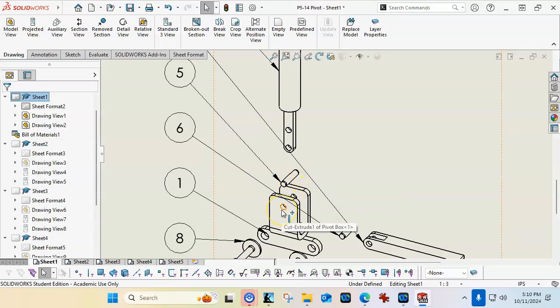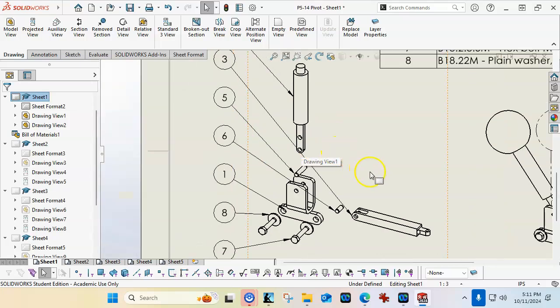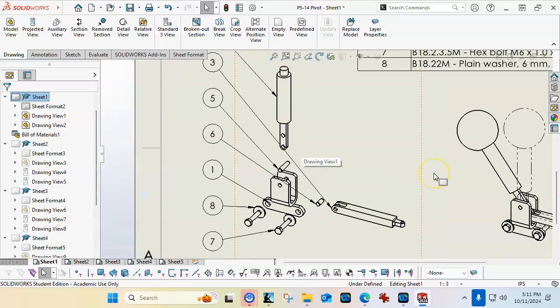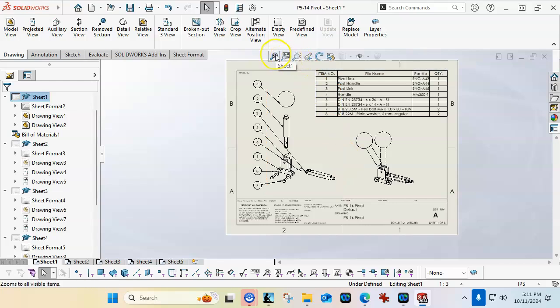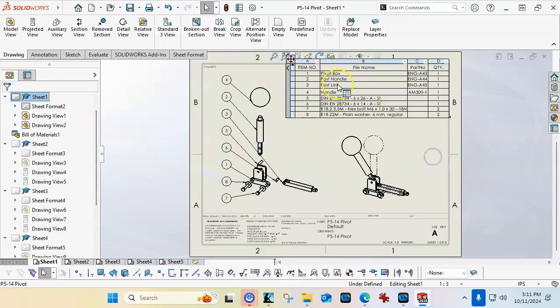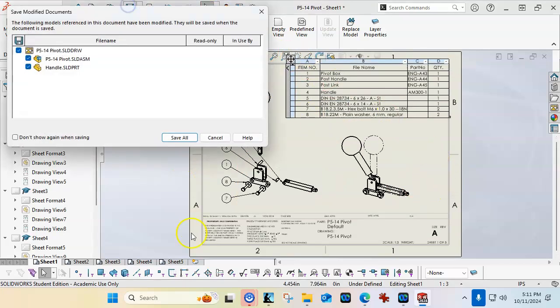Is this also a press fit? Is this going to be able to slide back and forth? There's a few things that, because of the fits and clearances and the movements and motion, that we have lots of clearance, but we have to determine what exactly it is that we want to allow to move.